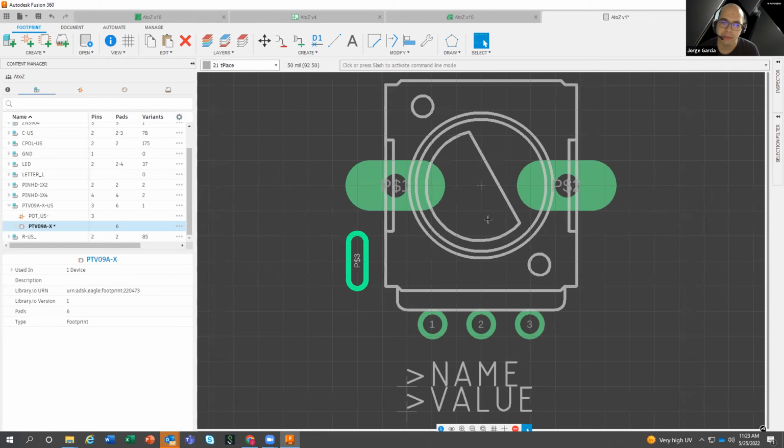So anybody who has libraries that use the workaround, which Richard was mentioning, basically you draw on the milling layer, and then you have to send a separate Gerber to the manufacturer. You have to let them know, hey, these are my milling features. Make sure you cut them out. And you have all this back and forth with them. Now they're properly supported. They'll come out in the Gerber as expected.